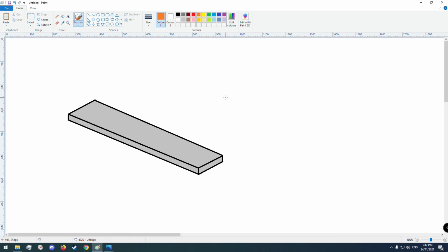The main thing a magnetic field inside a speaker affects is a spec called the BL. The BL is very simply the magnetic field, which is the B, times the length of wire inside the magnetic field. It's measured in newtons per amp.